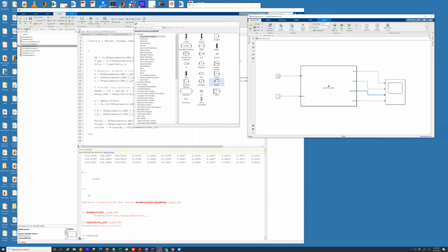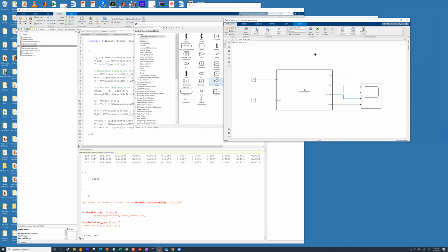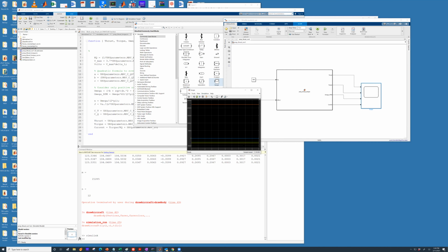This is super important just to make sure that this block is working, because many a times the MATLAB code on its own will not work if the data structures are not mapped correctly. Say run. And when you run, if everything is good, you will get some output from this block. Please note, this is just a constant output because we are supplying constant airspeed.